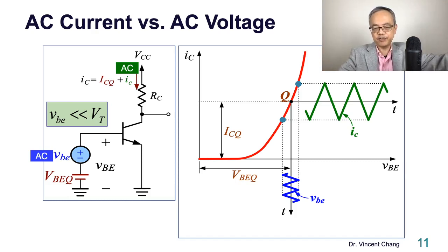If you go back to the previous lecture, the definition for the MOSFET's small signal is much less than the overdrive, VGS minus threshold voltage. But here, it must be much less than the thermal voltage, 25 millivolt. So 0.1 volt is too large, 100 millivolt is too big. Usually it has to be 5 millivolt, yes, or 2 millivolt, yes, it's a small signal.